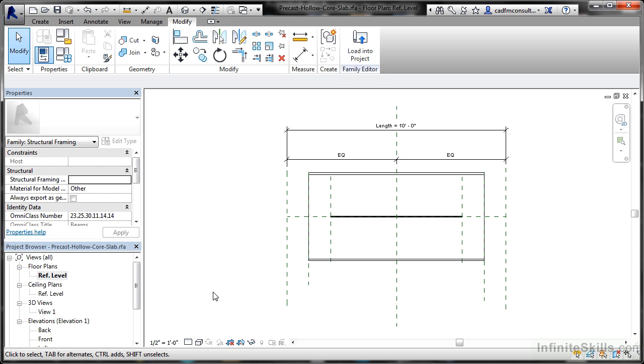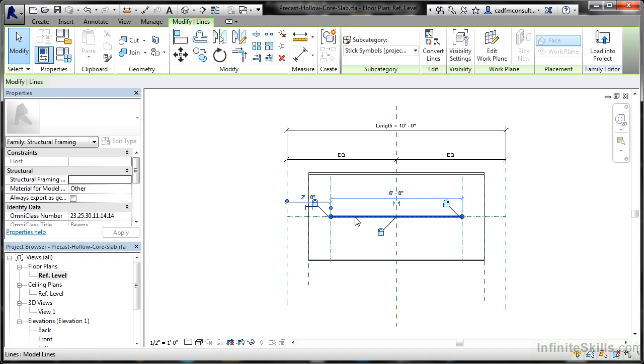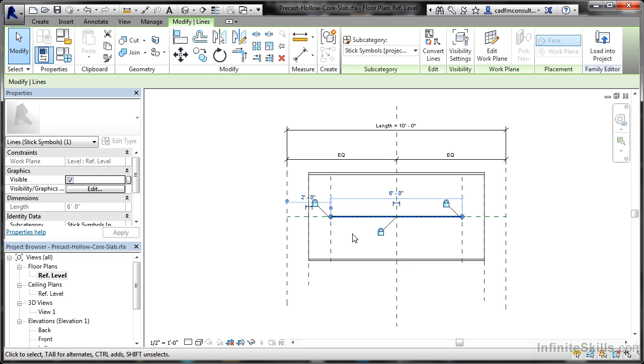At the moment, there's nothing hidden on there. There's no hidden lines at all. What we need to do is select the heavy model line here. If I select that, you can see there's the model line, and it gives me the option to set various things in the model. That model line will display in the plan view with the coarse detail setting. I'm now going to set the visual style to wireframe because it knows that I've selected the slab.